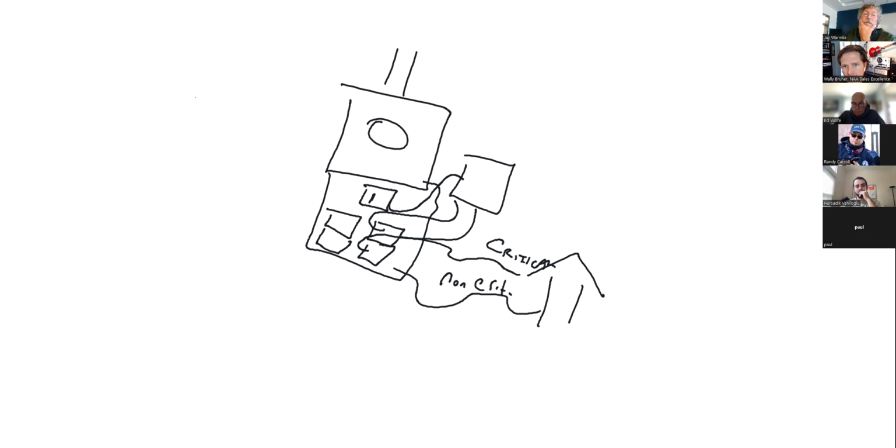But if it's a relatively small house, and you're willing to do load management, you may as well just have your whole house as critical loads. That's what I'm thinking. And then we just manually manage it. The appliance that's going to have the most load is going to be the oven, and probably the dryer. And we just don't run those. Or within your service panel in the house, you're going to have a lot of breakers going out. You can just flip the breakers off for what we're not going to use.